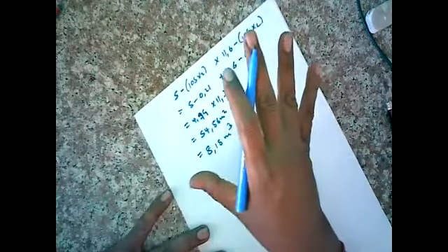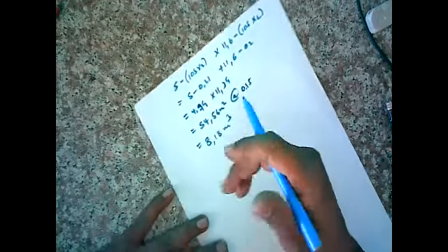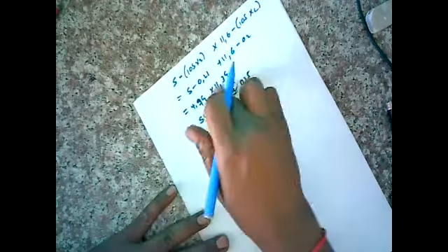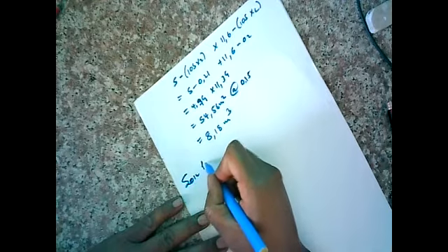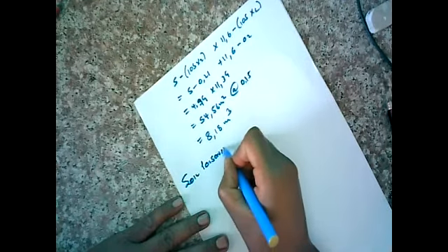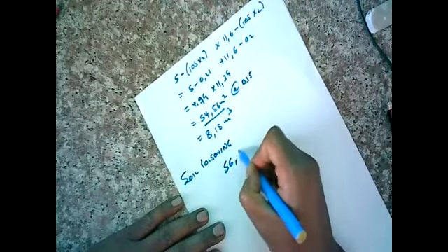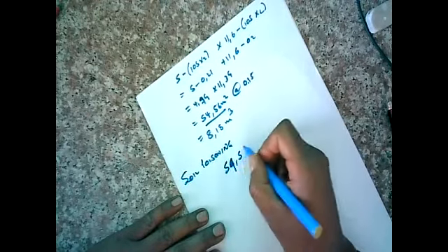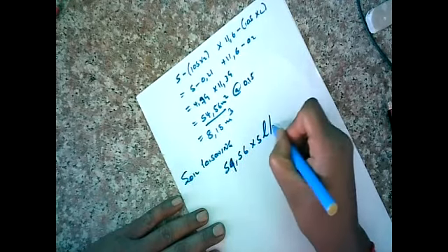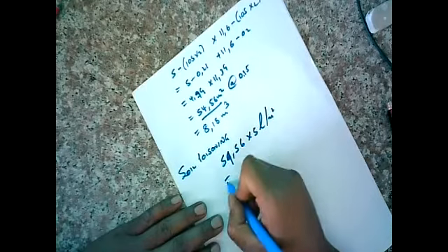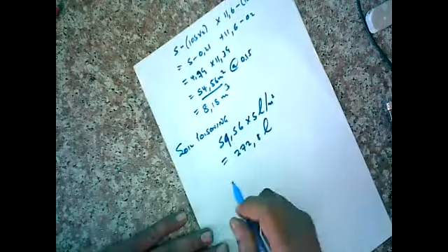Why are we still with the floor slab? Let's put in the soil poisoning and do the calculation for the reinforcement, because we're familiar with the values now. So soil poisoning: 5 liters per meter squared, and we're getting a value of 272.8 liters of soil poison.